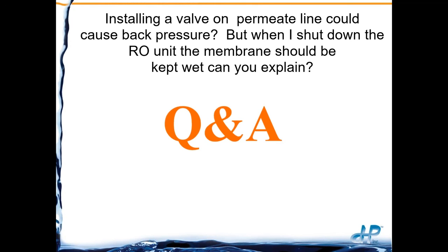One of the reasons why they'll do this is, let's say you have a storage tank that RO permeate is going into. Generally speaking, they'll have a pipe coming up to the very top of your storage tank, and that'll keep water going back into that on the permeate side. Keep in mind also, there are going to be check valves on your permeate side, keeping back pressure from going back, or from keeping the osmosis from completely draining your permeate side.